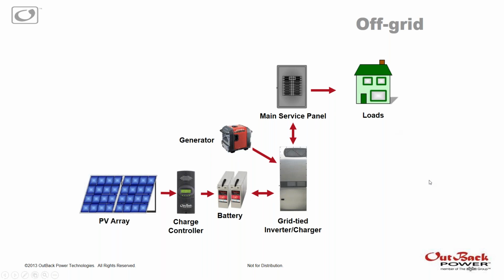We've lost this sub-panel because now the inverter is going to need to provide everything. In the case of a home that maybe previously was connected to the grid, some of these loads, perhaps maybe a pool heater or something that isn't quite as important as some other loads, if the loads in the main panel exceed what the inverter can supply, it may be necessary to turn off a few breakers so that you don't have issues where the inverter gets overloaded from the loads in the customer's home.